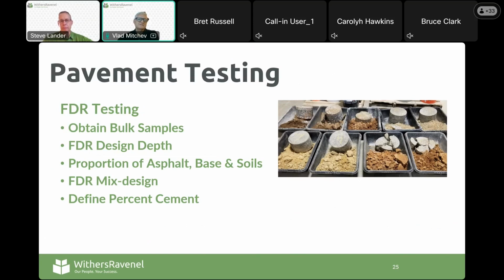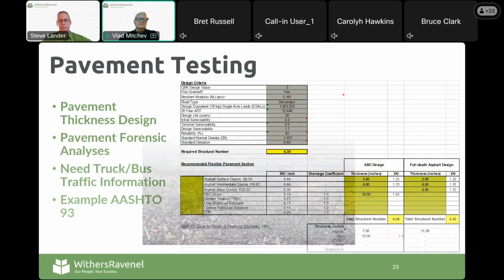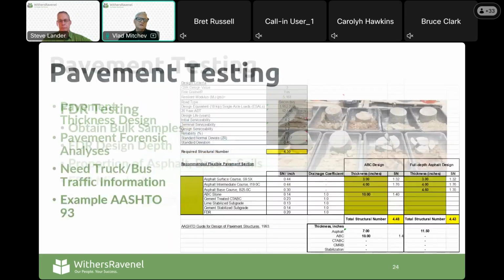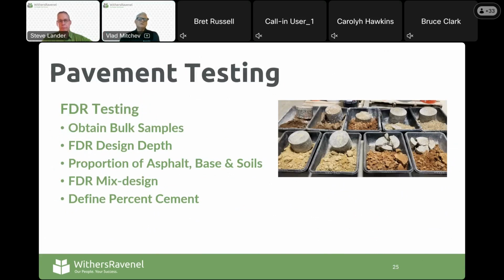So that's great value to a section here in the road, and we not only were able to mitigate the potential reflective crack issues that we could have had if we had only milled and filled, but we extended the pavement service life, because FDR with an overlay of a minimum of 2 inches of asphalt can last 20-25 years without any additional treatments on it.